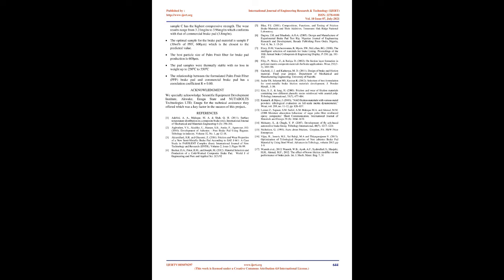Again, from the result generated showing the contour diagram of the relationship between two variables, i.e., palm fruit fiber, A, and binder, epoxy resin, B, to the hardness value of the samples developed for the brake pad, Figure 7, it can be inferred that the value of the correlation coefficient, R, is about 0.29 for A while it is 0.80 at B. This shows that the binder, i.e., epoxy resin, contributes more in terms of hardness value for the material developed. Figure 7 shows the 3D surface plot of the relationship between three variables to the hardness value of the samples developed of the brake pad.